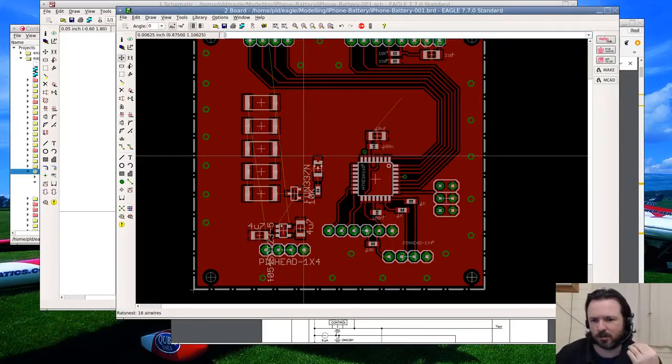because we know already that the batteries are going to be at least 1500, 1300 milliamp hour. So we don't need any restrictions in our current control. We don't have to adjust the voltage. We don't have to have sensing like that. Perhaps we can have a second button as a mode button. Say maybe you only want a single cycle check, so it just does a charge, discharge, charge. Or you can maybe set it to unlimited. So that would leave you with two buttons then: start/stop, and mode select.